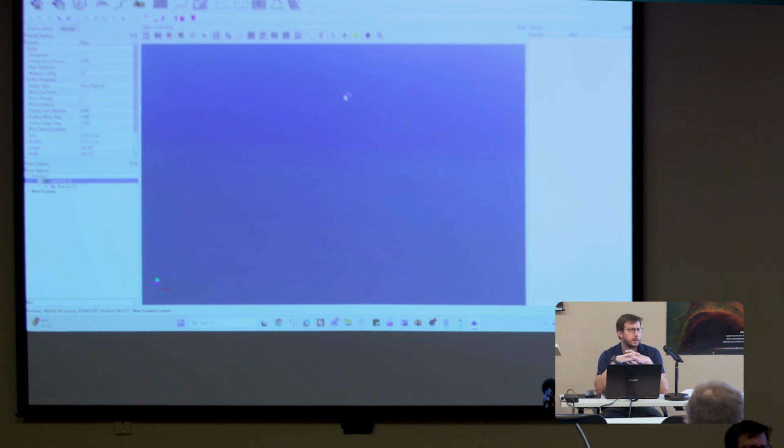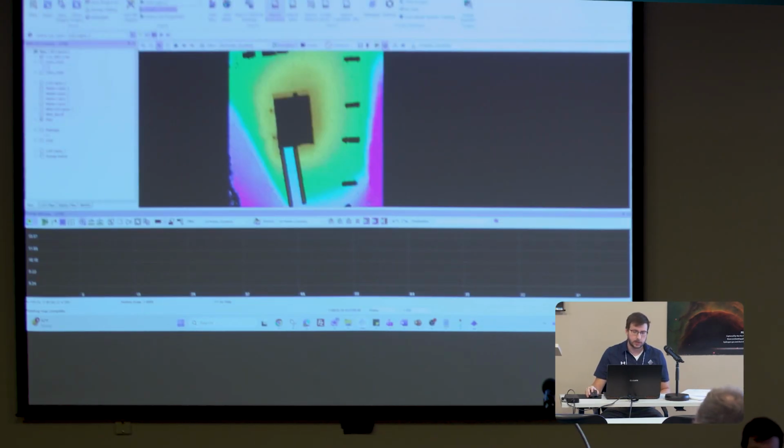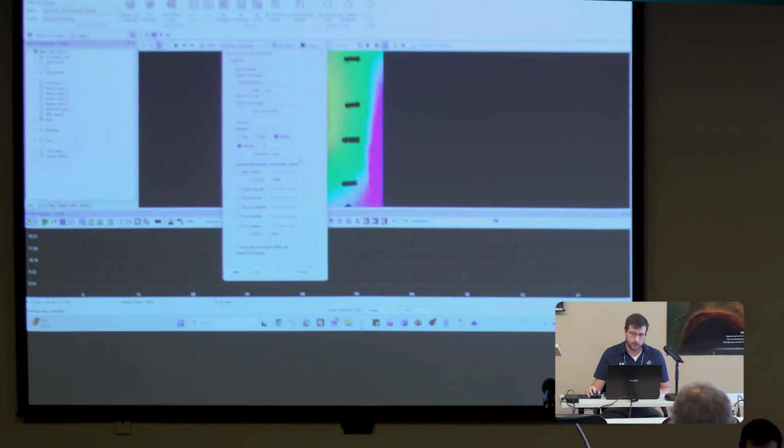Question. Yeah. So on ground fitting, what specs are we trying to nail, that 8 points per square meter? Okay, that's a very good question. So if you're trying to get to 8 points per square meter, I'm going to go to the point task, go to active PCT settings for the thinning task. You would set the units to meters here at the top, cell size of 1, and then put in 8 there, and then you're good.